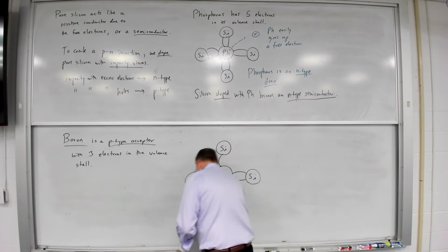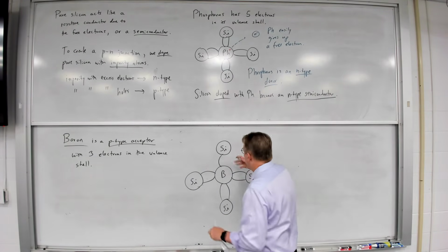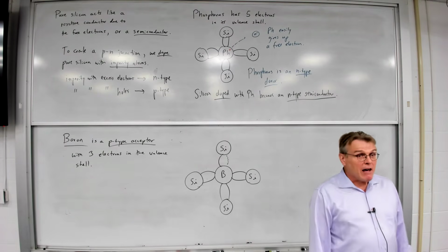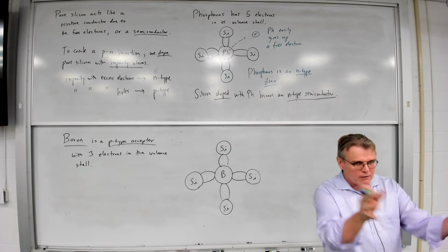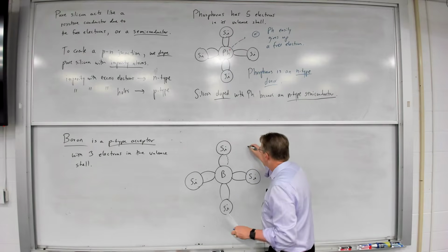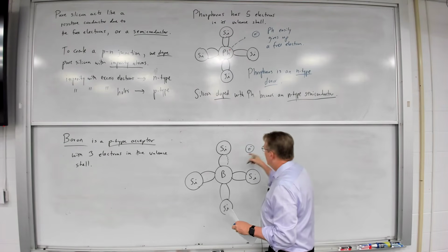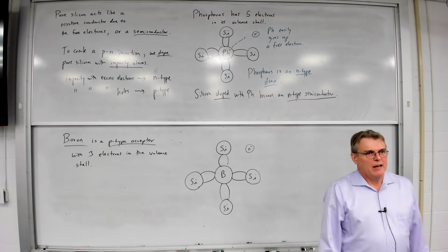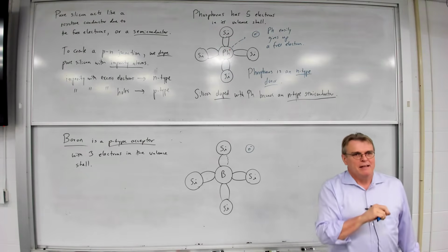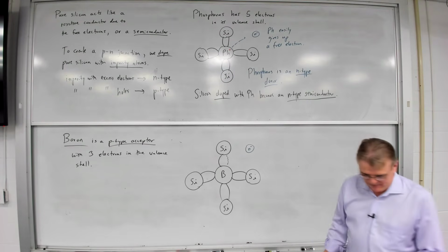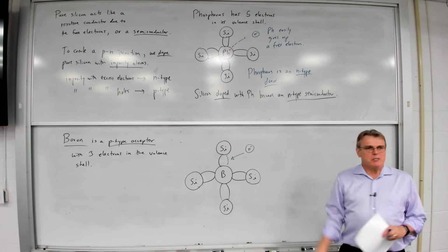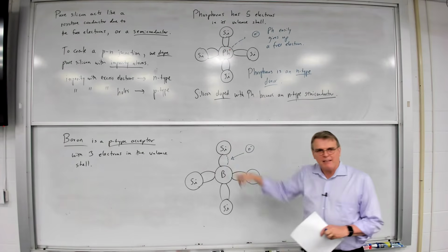So in this case, what we have here is a place where that boron would love to have an electron to complete those 4 covalent bonds. So what will happen is a free electron comes drifting along, and if one shows up, that boron atom will grab that to complete its outer valence shell. So in this case, it accepts a free electron to complete that 4th covalent bond.